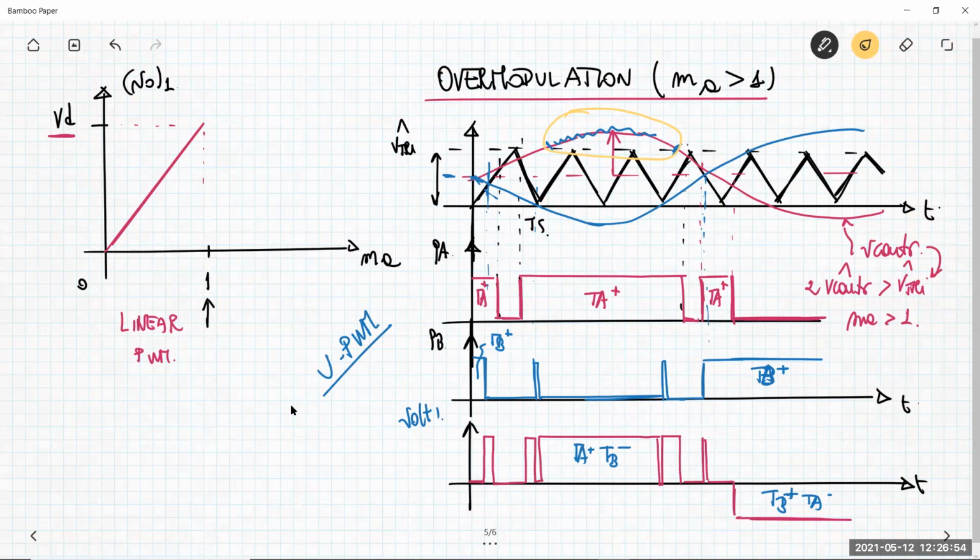What does this mean in terms of comparison between a control voltage and a triangular waveform? That in this region here, we have no possibility to use the comparison between the control voltage and the carrier waveform, the triangular waveform, in order to modulate the unitary switching function width. Even if in this region here the control voltage is changing, it's not constant, this variation of the control voltage is not taken into account in the unitary switching function.